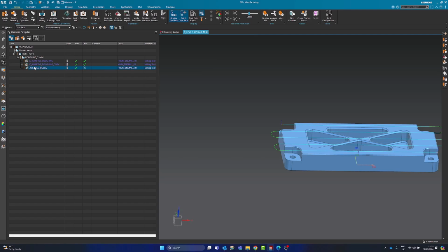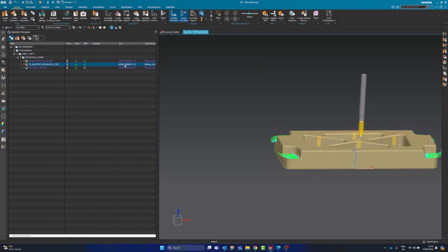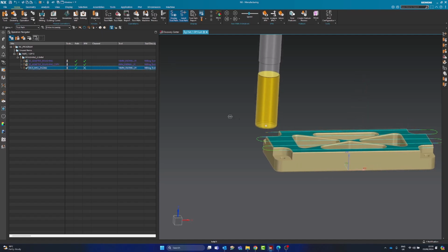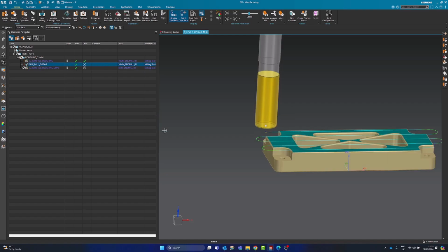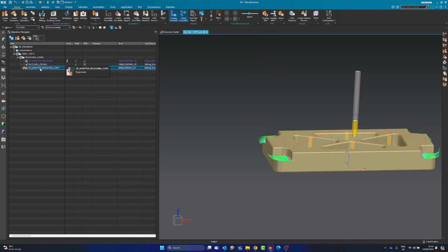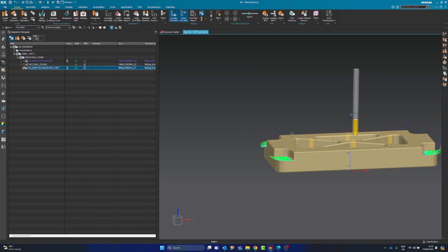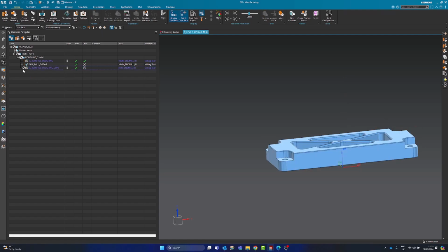Spot on. Okay, because we have the 16mm here, and then the 4mm, and then the 16mm, you're going to have multiple tool changes, and that doesn't make sense in this case. So let's drag this tool to be above this one, and you can see here it's saying the stock has changed because we've dragged this above this toolpath. The stock that it now sees for this toolpath is slightly different because now it's not got 2mm on this top face. So you can see it's gone ungenerated here.